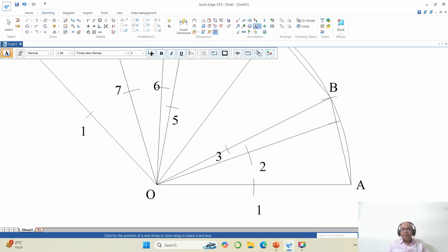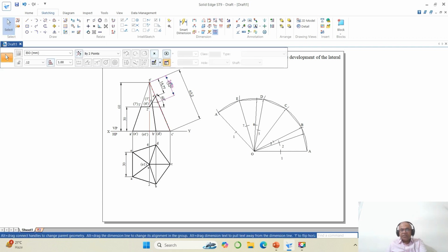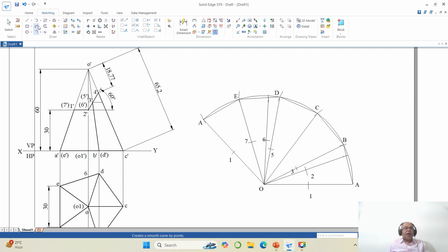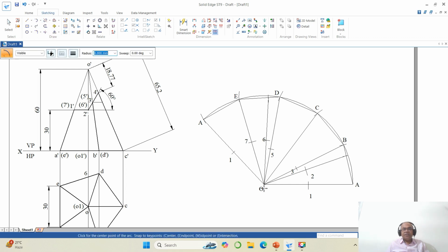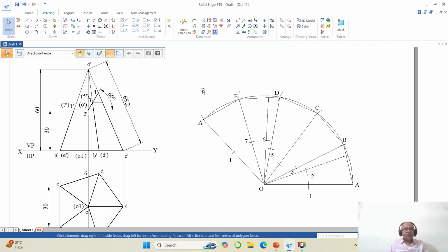Okay, next, split it. Now again you go to fit, remove this. So now we have 18.77. So go to move, go to arc. You have only one arc which is radius 18.77. Sweep angle is 15 degrees. You take that and you keep it here. So this is going to be 4. So you delete this. Then you bring this nearer to this. Okay, once you do that.